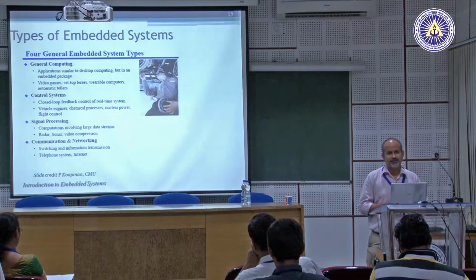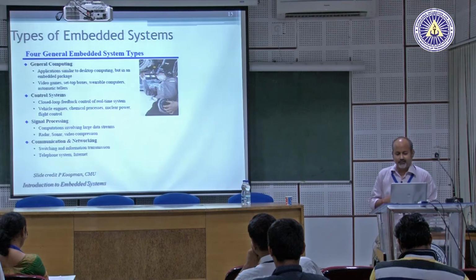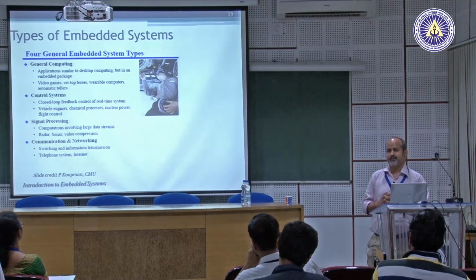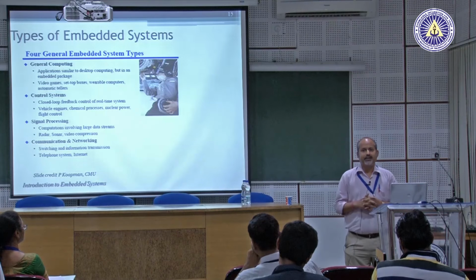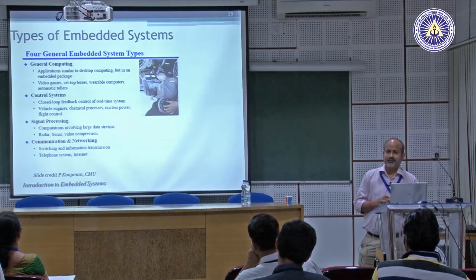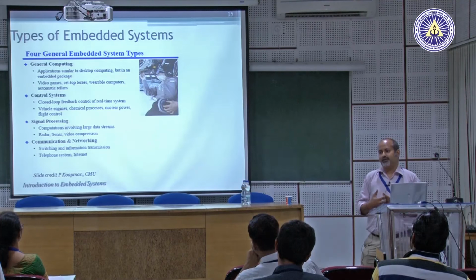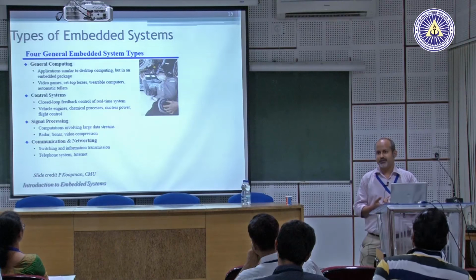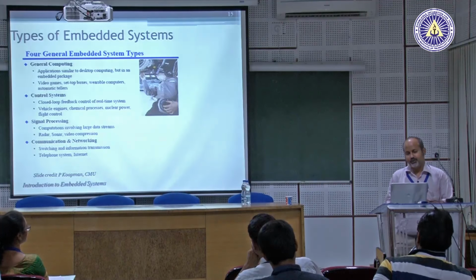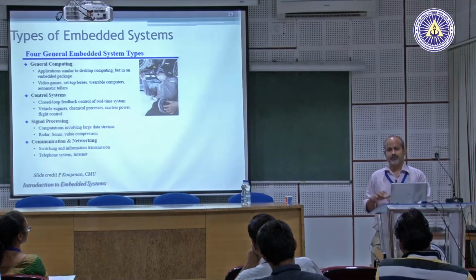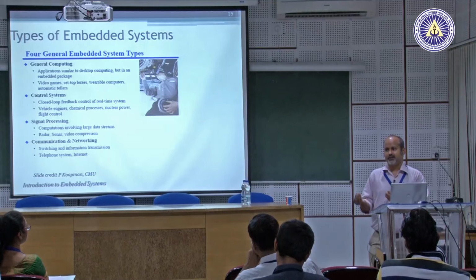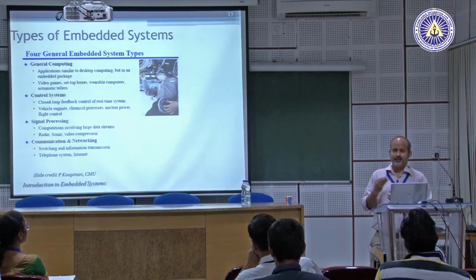So open loop control are simple things, but whenever you have closed loop control, you have sensors and actuators in the system, right? And the sensors are the ones that tell you about the current state of your system through some measurements. And from those measurements, you construct what is called a state estimation. You try to understand your system state. And when you estimate your state, then you know exactly what you have to do to change the state so that you are closer to where you want to be, because there is a control trajectory that you want to be in order to make things work.